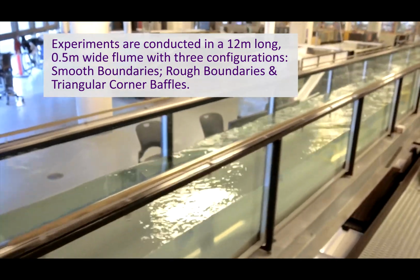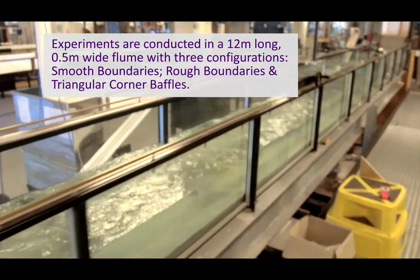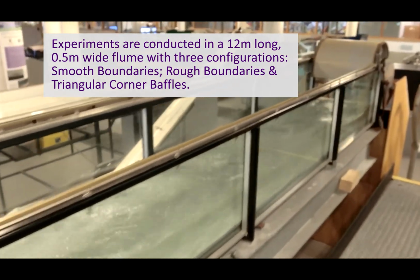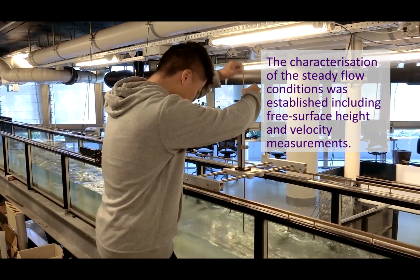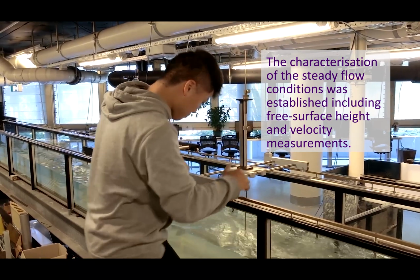Experiments are conducted in a 12 by 0.5 metre flume emulating a near full-scale culvert. The three configurations tested were smooth boundaries, rough boundaries, and triangular corner baffles at intervals. The first step was to characterise the steady flow conditions for each of the configurations, which included taking the free surface height and velocity measurements.